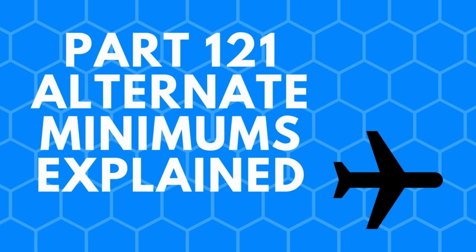1. Adding 400 feet to the authorized CAT-I height above airport, HAA/height above touchdown elevation, HAT, for ceiling. 2. Adding 1 mile to the authorized CAT-I visibility for visibility minimums. This is one example of the criteria required for Part 121 operators when calculating minimums.